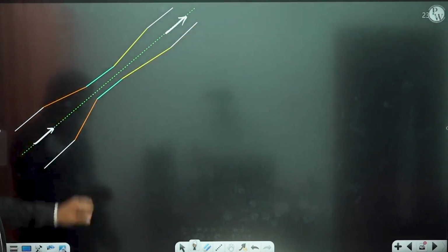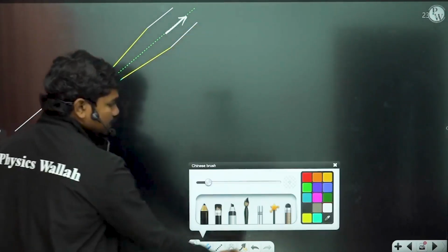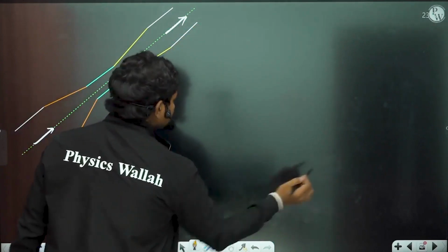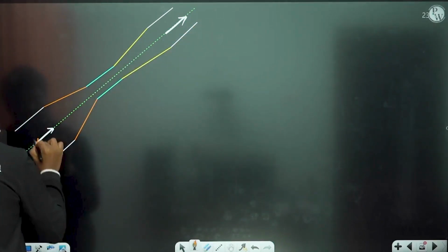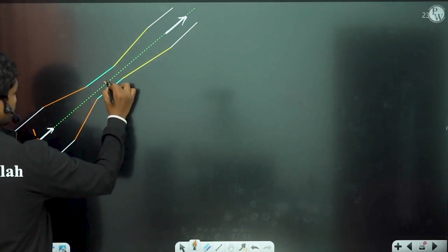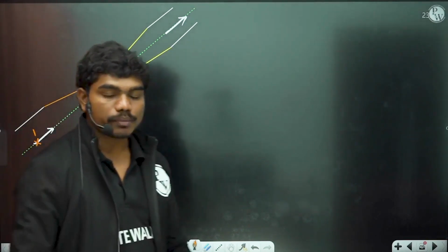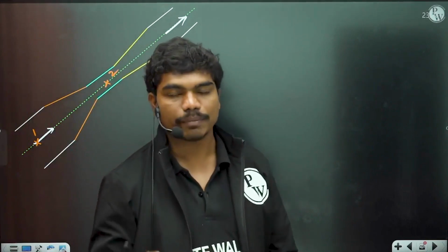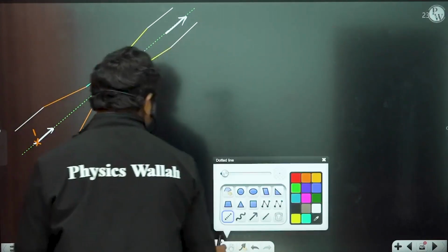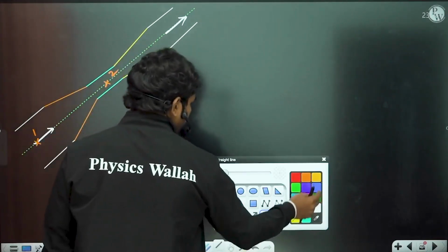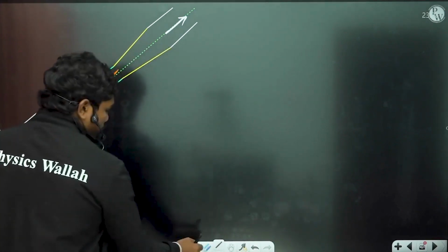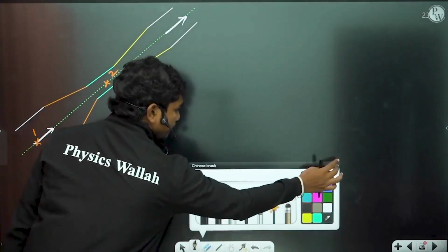Now basically you want the pressure difference at these two locations, to calculate the discharge. So this is location 1 for example, and this is location 2 at the throat. They'll ask you why you will connect the manometer only at the throat and the pipe. Okay, so let me show you first of all how it is connected. So see carefully.